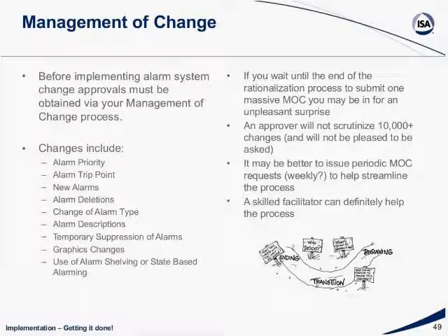But the other thing also, as you do your approvals, let's say on a weekly basis or whatever it happens to be, then you can start doing the incremental implementations, okay? Your alarm management champion can update the master alarm database and then do the implementation. The benefit of this is that, number one, you're getting the benefits of your rationalization sooner. Number two, when you monitor the new system performance, you see how much closer you're getting to your ISA-defined metrics as far as the alarms per day. And so you will know pretty much how much longer you have to continue the rationalization process.